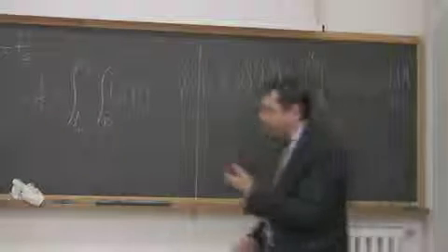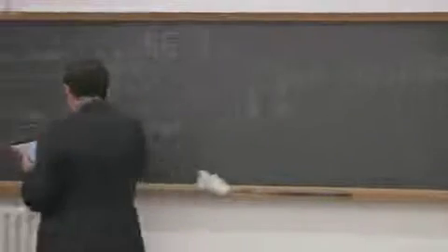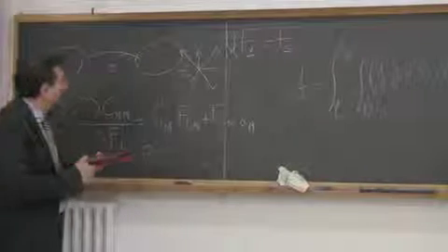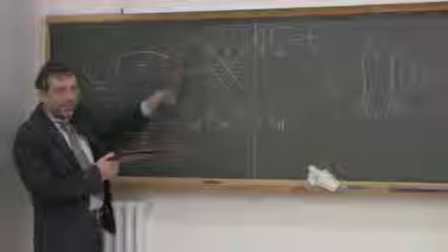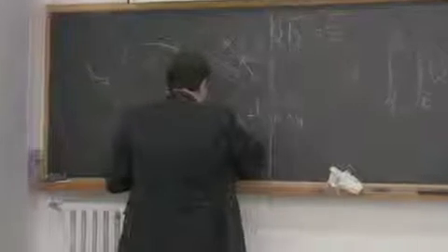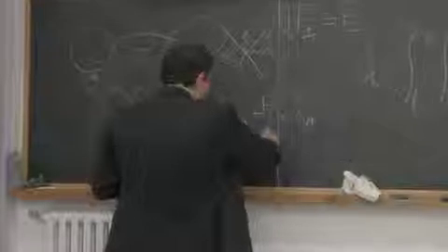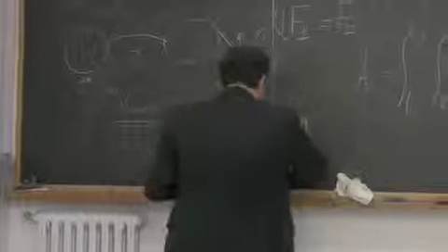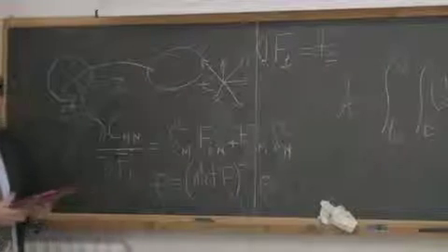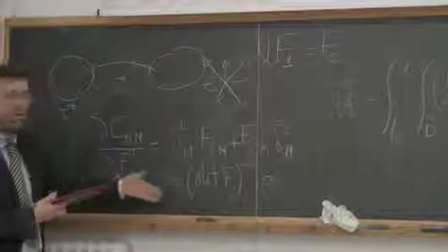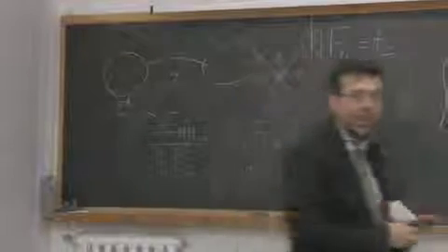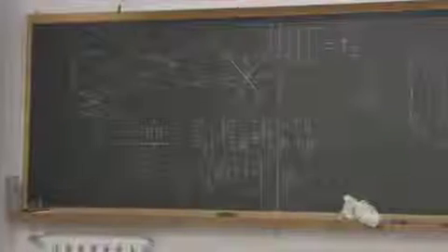Now, a formula which we will not need immediately, but it is clear, is this one. The mass density in the actual configuration is equal to the determinant of F to the minus 1 times rho 0. This is a kinematic condition which is included in the theorem of change of variables in the integrals, which is standard.